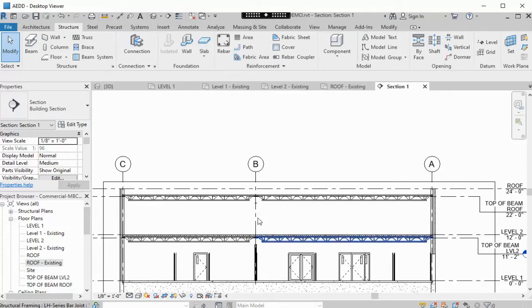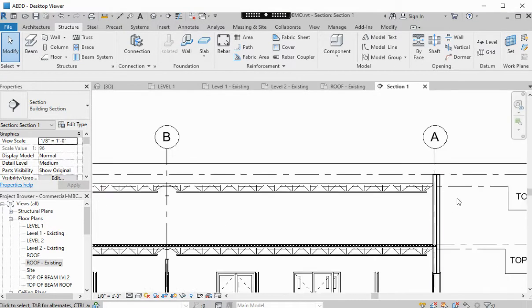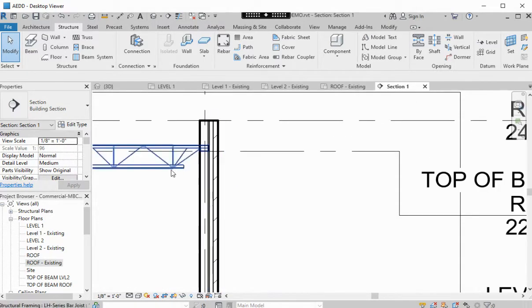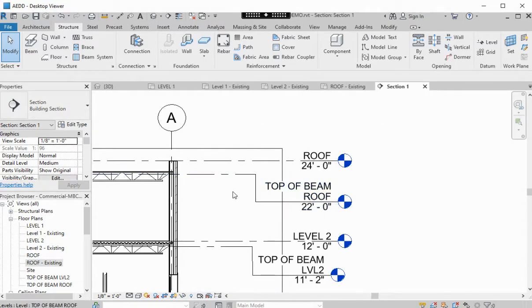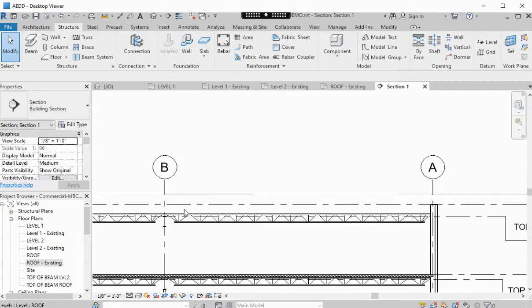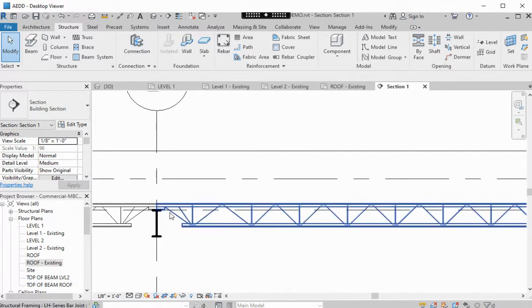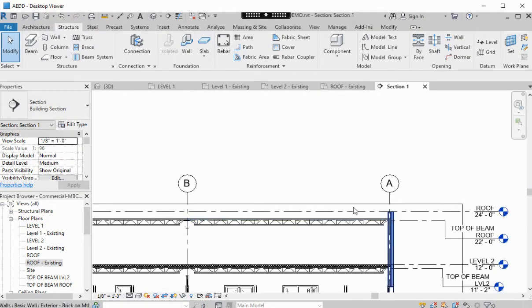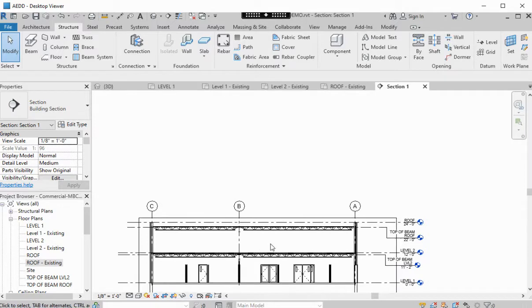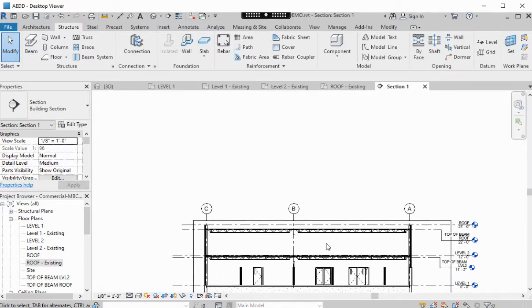Being added to the first and second floor, so you should have done this second part on your own. Make sure that the beam is attached to the correct work level of top of beam roof, and then you're going to make sure you're attaching these to the same level but adding 5 inches to them so they sit on top of the beam. And so now what I'm going to do is show you how to create the tapered insulation roof system.